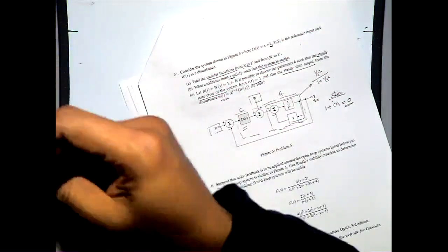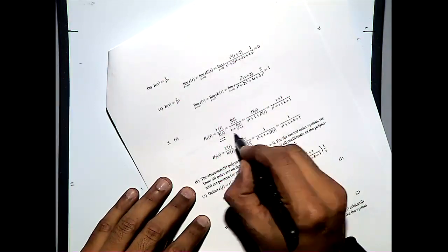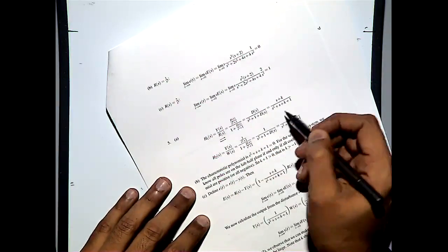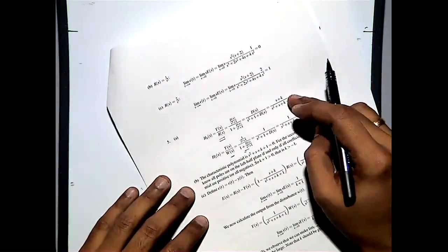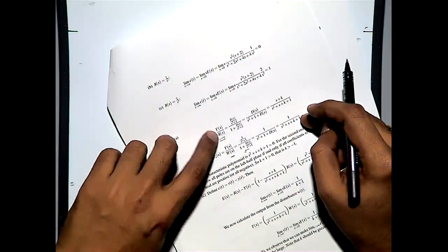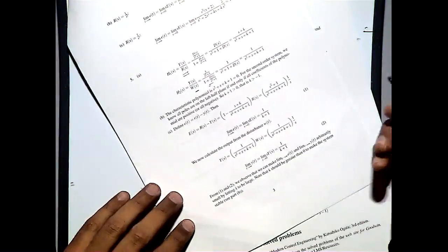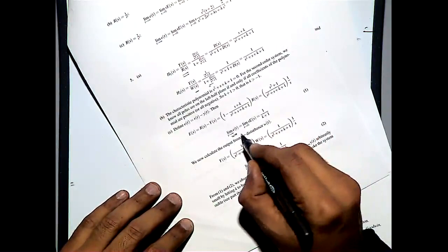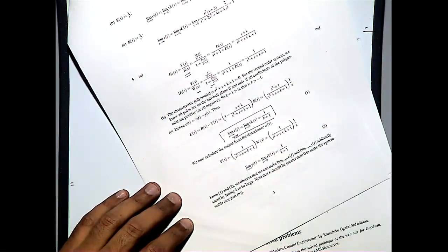So it turns out that the solution will look like this one. So the transfer function model of that one is given by the equivalent sensitivity functions here, and you can find out the transfer function models for r to y as well as from w to y here. So for finding out the steady state value, you apply the final value theorem.